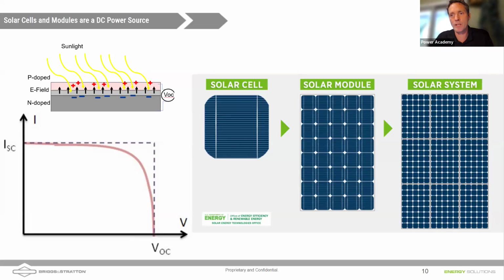So when the sunlight comes in, it excites electrons, and there's a built-in electric field which pumps the electrons down in the solar cell, creating a deficiency on the top of the cell, the positive side of the cell, and creating an electron-rich section on the bottom side of the cell. And so if you look at the solar cells themselves, they have these collecting nickel strips on top of them to carry the electricity that's generated, and each cell kicks out about 0.62 volts, right?